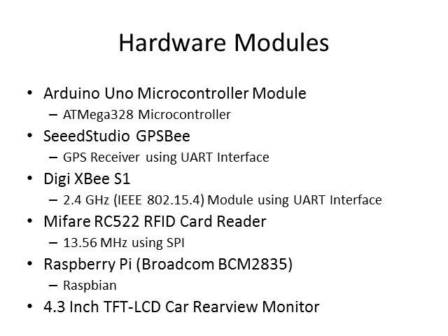Now, in order for the Decision Subsystem to carry out these logic flows, the backpack has to provide the Decision Subsystem with a certain amount of data. This data comes from these hardware modules, as you can see here. The hardware modules include an Arduino Uno, a GPS, an XBee, and an RFID card reader. The Arduino microcontroller has the ability to control each of these three units, the RFID, the GPS, and the XBee, to perform certain functions and push sensor data to the DSS.